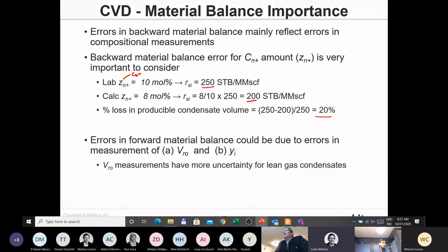Just a comment, Bilal. This is also reflecting the initial condensate in place number. It's the same number. Let's say that our reservoir contains 1 trillion standard cubic feet of sales gas. That would mean you've got 250 million stock tank barrels initially in place, of which you might be recovering 30%, which obviously is a lot of condensate.